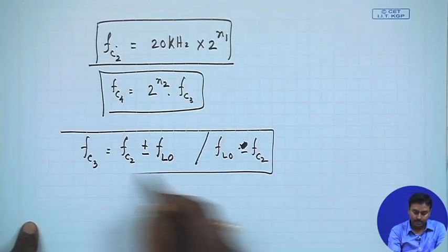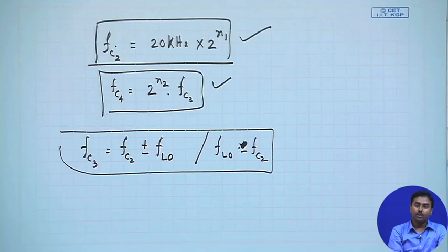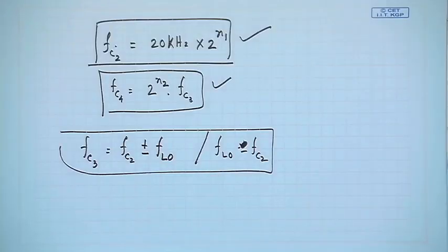So, this equation and this equation, wherever it satisfies that FLO is within 400 and 500 megahertz, as well as all n1 and n2 are integer values. If all these things are satisfiable, then only I can get a solution. So, what we will have to do is now start taking all 3 cases one by one. The solution I will not be doing, it is easy, you can do that. The solution will be just take one by one, for each case try to see if we get something meaningful. You try to calculate the FLO from this particular equation.